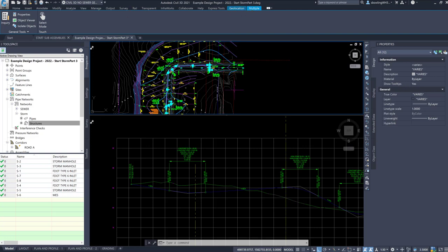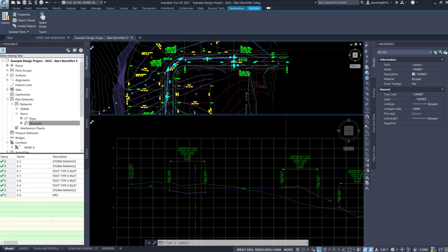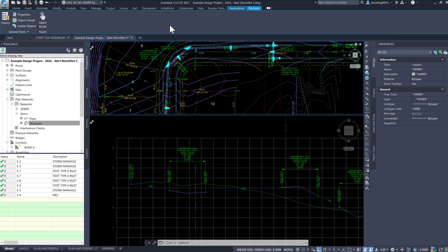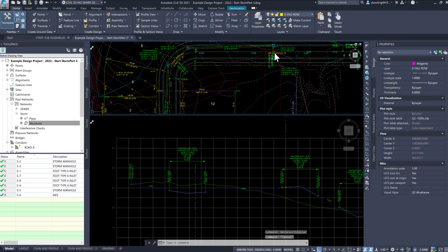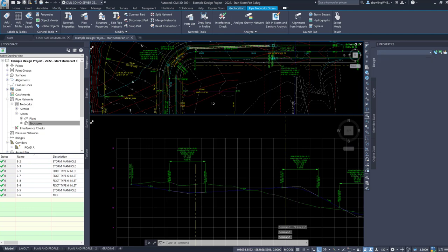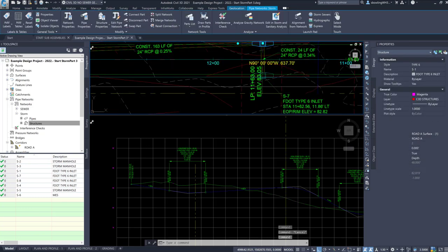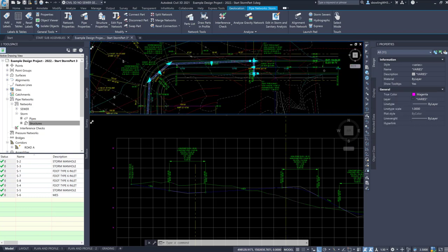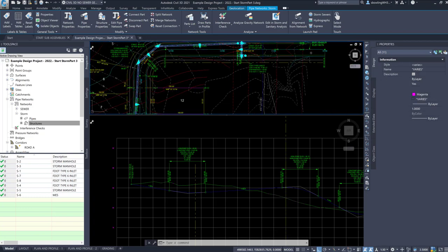And I am going to... Oh, I didn't do what I wanted to do. Looks like I'm going to be selecting them individually. I should have been able to just click on it, and then see how this pops up with this pipe network here? Now I'm going to go select similar. There we go. I must have been touching something else. So I only want the structure in the pipes and then select similar. Again, you can only do this if you only have one profile.